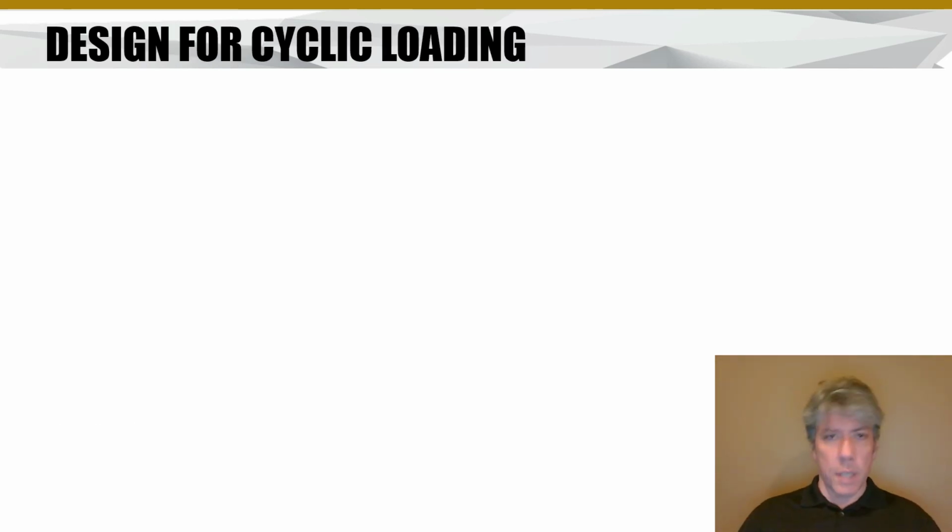Okay, so there's this thing called fatigue. How do we design to protect against it? What should we do? Well, it depends, because remember there's two parts to the fatigue load. There's the mean stress and the alternating stress, the stress amplitude.